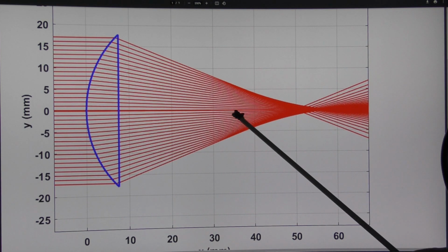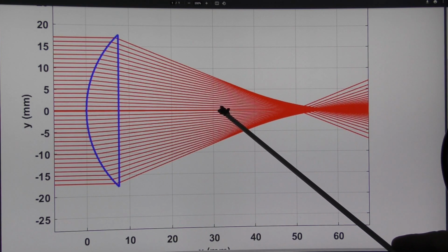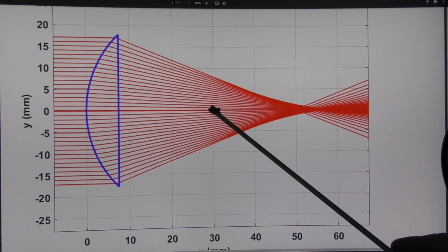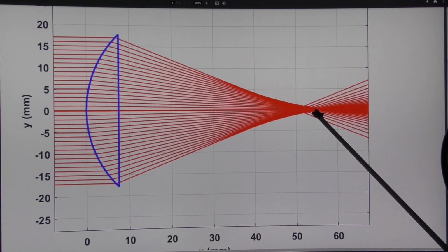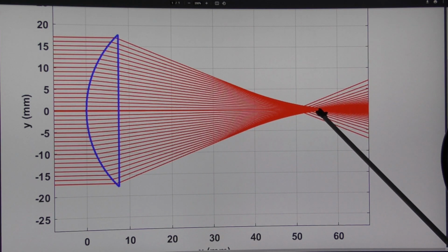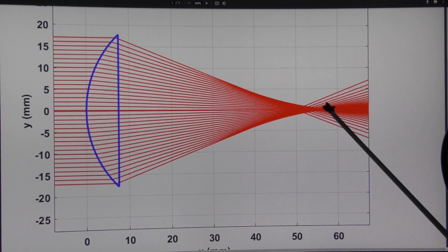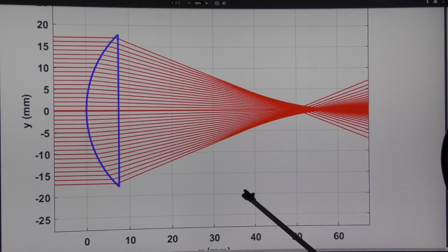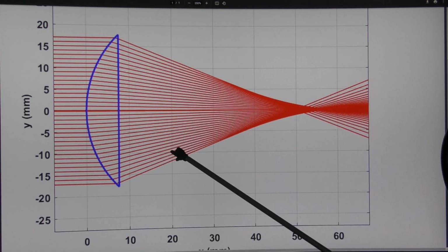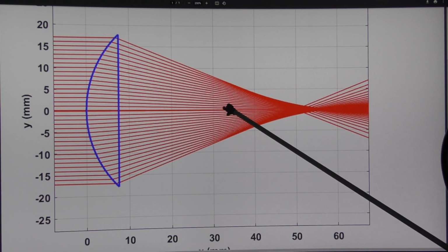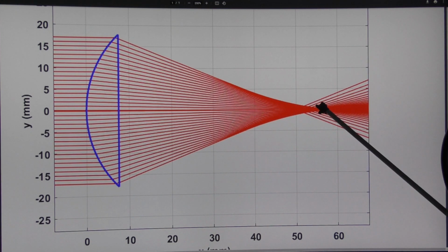But in addition to that, what we're finding is we've got these rays which are close to the beam axis, which have still got lots and lots of power, and they're passing through this hole that we've created at the top of the acrylic, and they're going into the void that's below, and they have got enough power to still damage the edge of the hole that's been created by this parallel bit that's gone ahead of it. I can see this so clearly in my mind, how all these different intensity but very high intensity rays around the centre are causing this effect which is happening below the focal point.